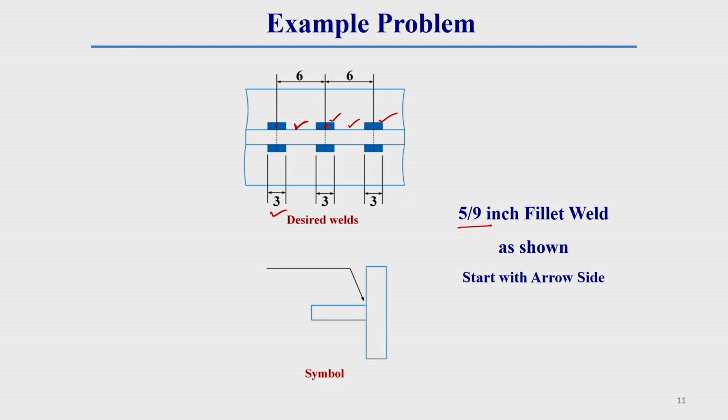How the welding is done, if we see the side view of this, we can get what type of welding operation is performed. The welding operation here is fillet welding. We provided both-side fillet welding, which is intermittent in nature.